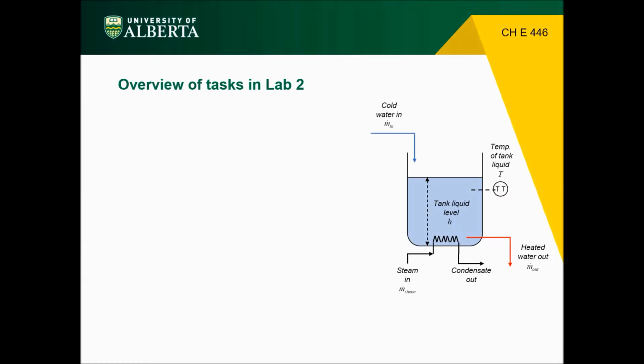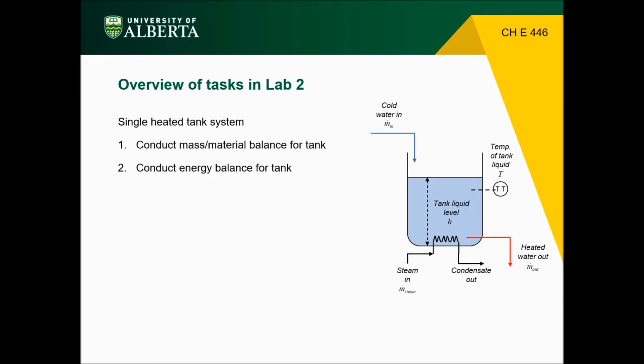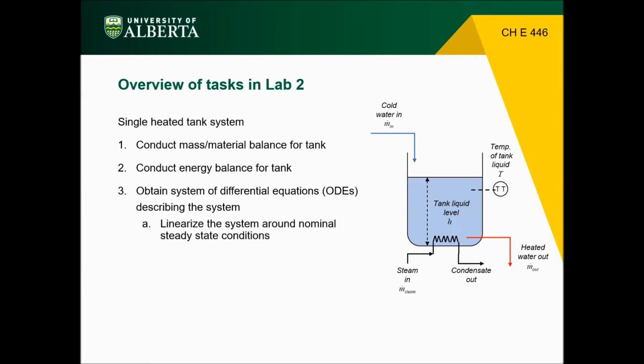Let us start with an overview of the task in Lab 2. For the single heated tank system, you are asked to conduct mass and energy balances for the tank. You are then asked to obtain a mathematical description of the tank system in the form of a system of differential equations. Then, you are asked to linearize the system around given steady-state conditions.